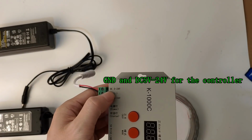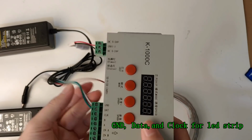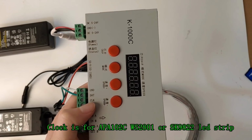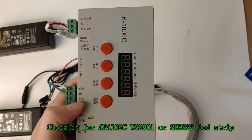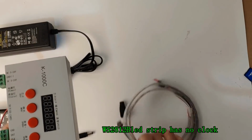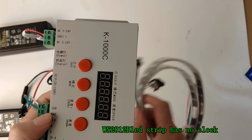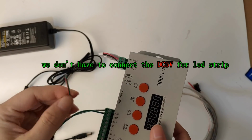The controller has DC 5 volt, GND, data and clock. The clock is for the APA102C or WS2801 LED strip. As for this LED strip, it has no clock, so we just use GND and data, and you don't have to connect this.